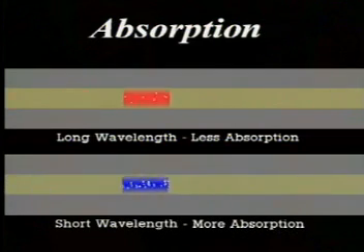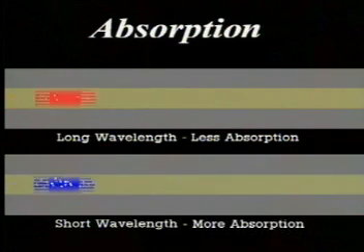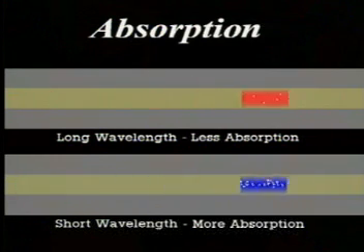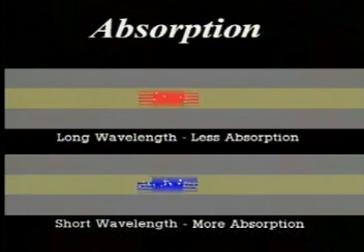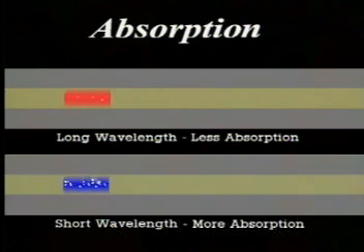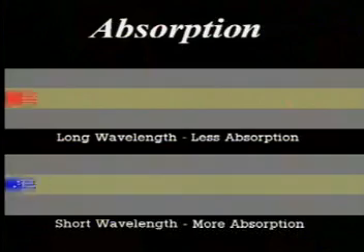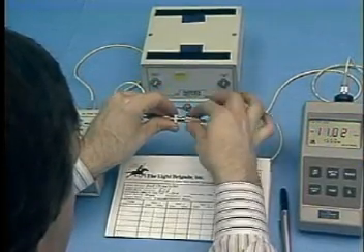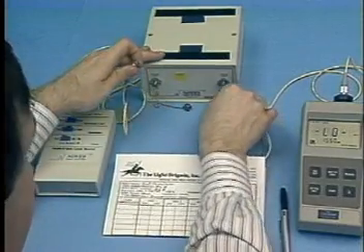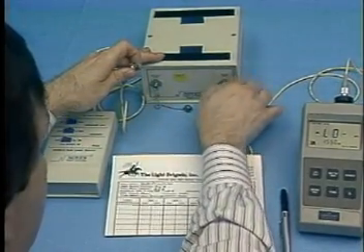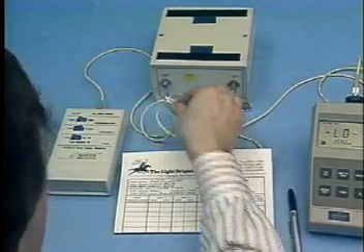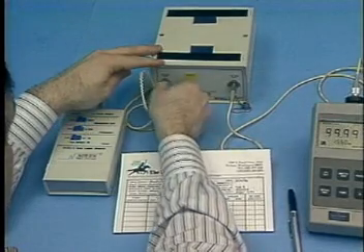Absorption losses in fiber are highly wavelength dependent. Shorter wavelengths tend to be absorbed more easily by impurities in the glass. The use of infrared wavelengths dramatically minimizes this effect. This is why a majority of fiber optics used in signal transmission have been designed for infrared wavelengths. The most common wavelengths used are 850, 1300, and 1550 nanometers. These wavelengths were chosen for the best performance with light sources, optical fiber, and optical detectors.